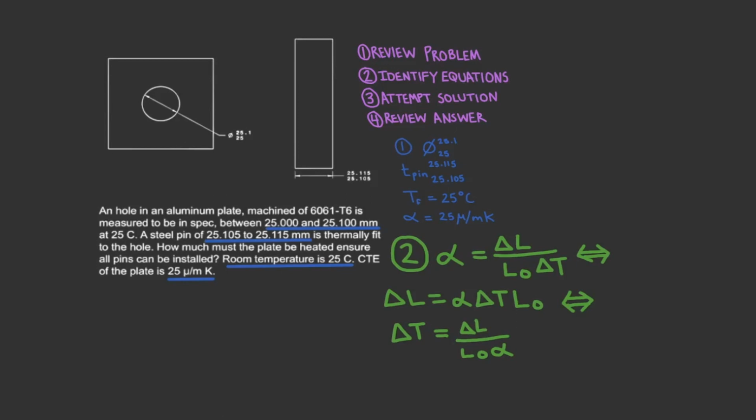There's one other concept we should be familiar with, however, and that is the 3 types of shaft hole fits. The first type of fit is a clearance fit. This means that all possible dimensions of the pin fit within the hole it's being joined to. In other words, there's clearance for the fit.